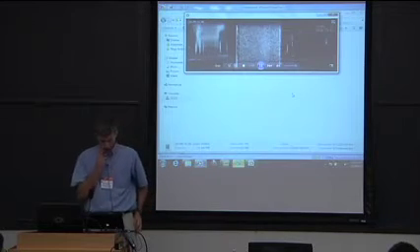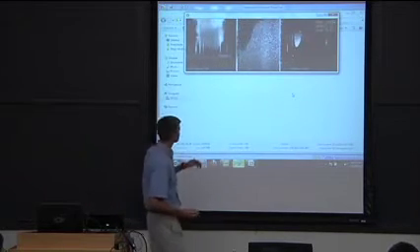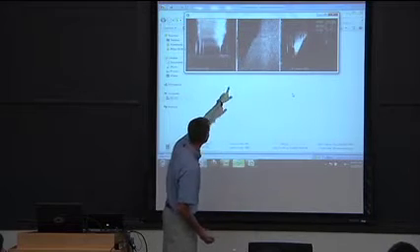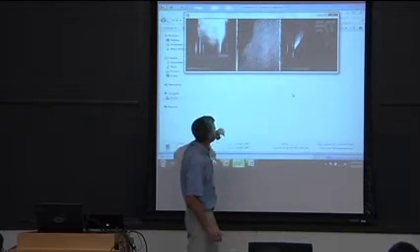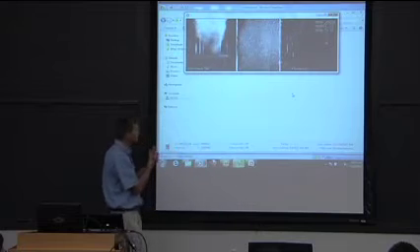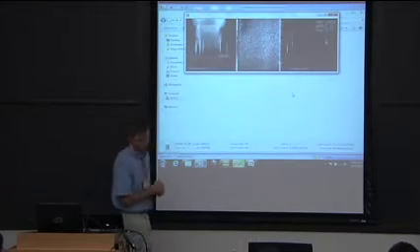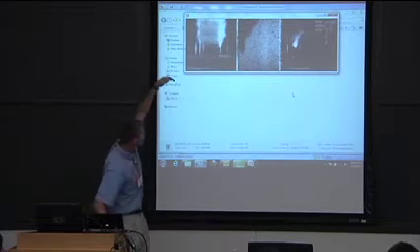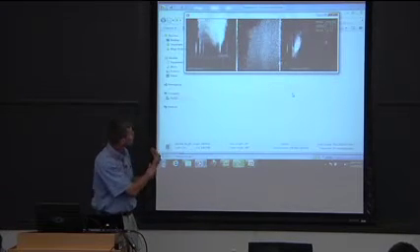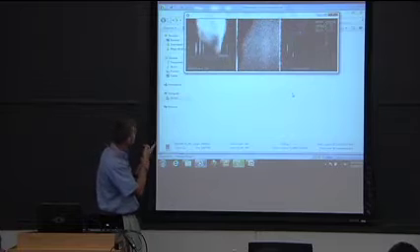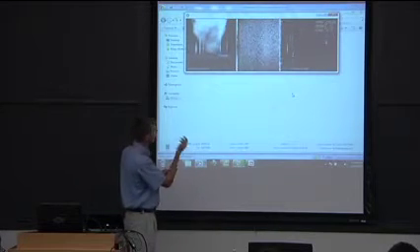And this is a flame shooting up the boundary layer. If we look on this side, this is a Mie scattering image. What you're looking at are PIV seed particles, and when the PIV seed particles go through the flame, these must be combustible seed particles because they go away.